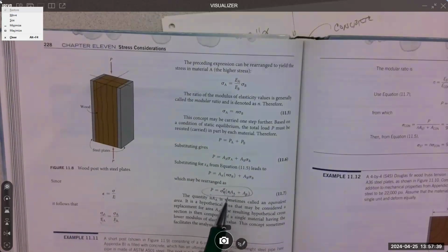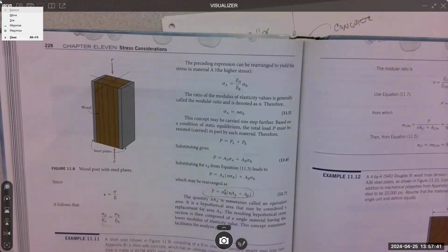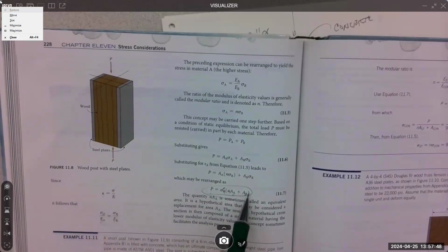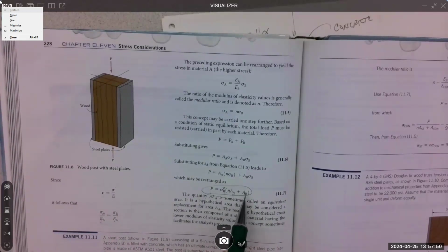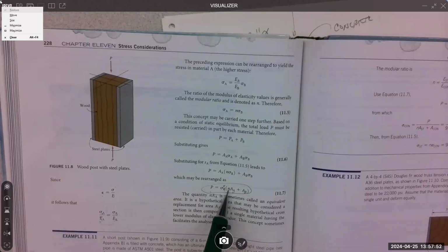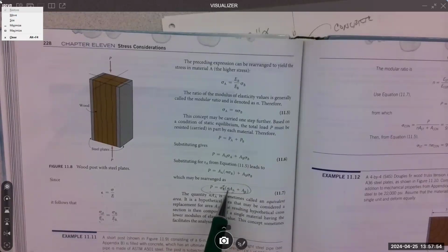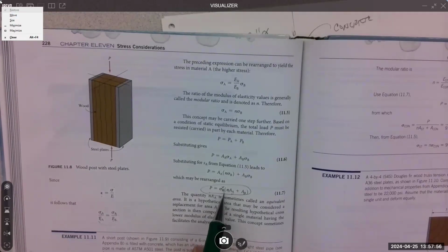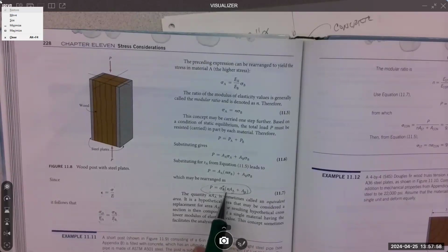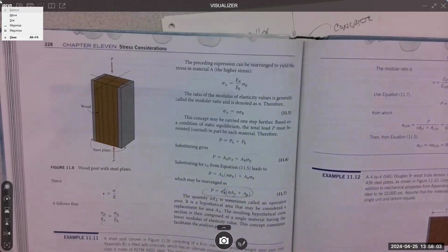So we allow the stress in B to rise to its limit. That's what we put in, stress in B. And then we don't even put in the stress in A, because the modular ratio is handling that for us. So combined materials run this equation. So for our problem, it would be stress of the concrete, like if we can calculate it real quick.